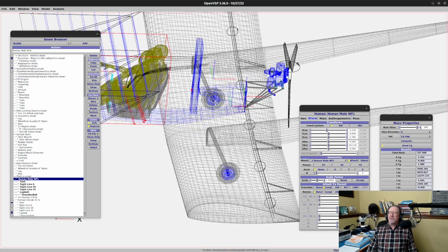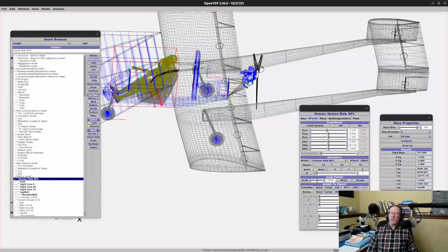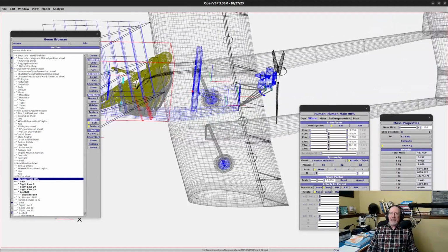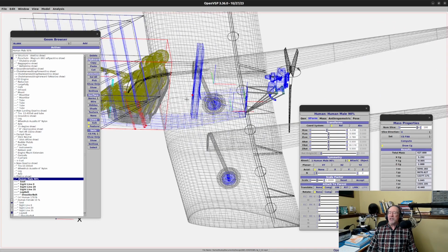I'll also have to figure out weights for the engine mount. The engine also will be a part of figuring that out, the rollover. I'll probably be able to design that and not have to change it. That's part of the fuselage. Where it attaches to the wing, I should be able to come up with a fairly final design on that, so I'll be able to size that.